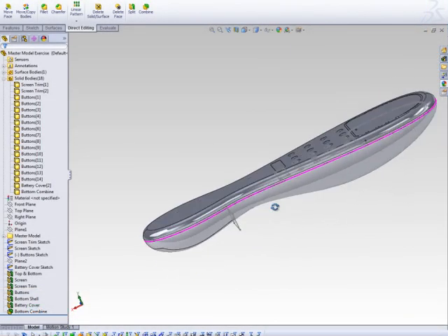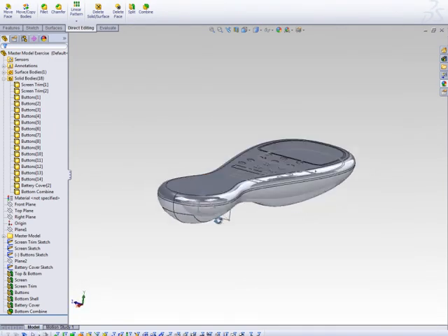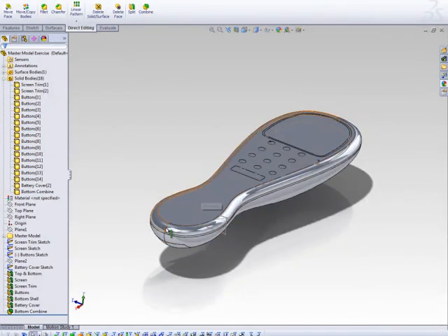This is part 2 of the master modelling exercise. The next thing we can do is look at different ways of using these components or sending them into an assembly. As discussed, there are two techniques. One would be classed as a push technique, where we are pushing components from our master model to create an assembly. The alternative technique is classed as a pull technique, where from the assembly we would pull components across from their individual part files.